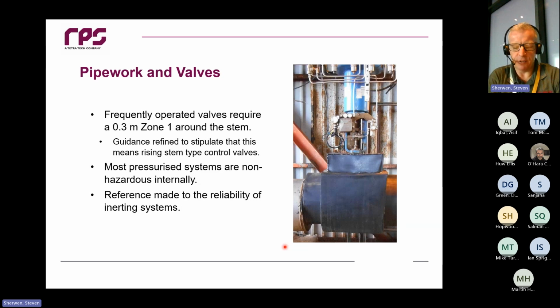We also have better language around pipework and vessel internals, to say that if you've got a pressurized system, the internals are non-hazardous because they're full of fuel and you haven't got any oxygen in there. Some wording has also been introduced about the reliability and applicability of inerting systems in the chemicals industry. As you probably know, a lot of the basis of safety is the inerting of vessels, so we talk about how that can be incorporated to lower your zoning, depending on the reliability of those systems.